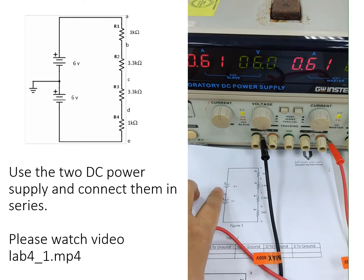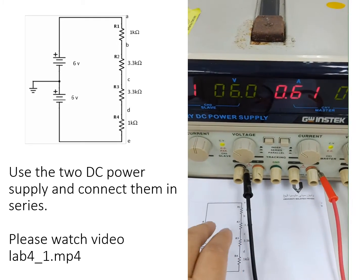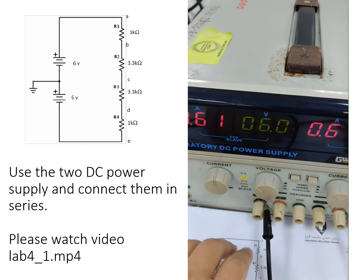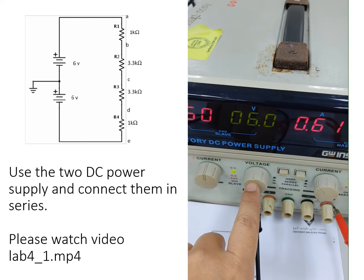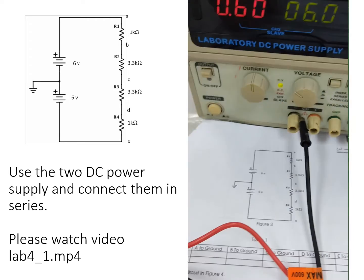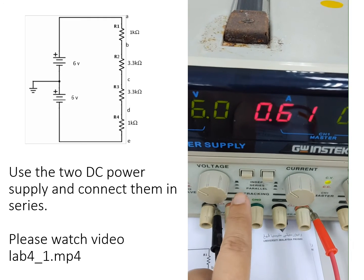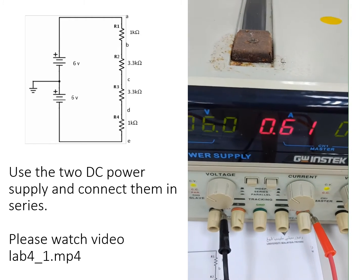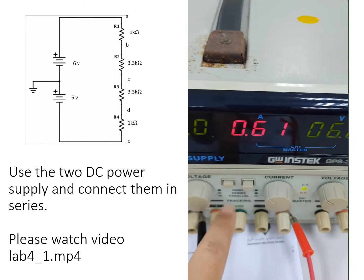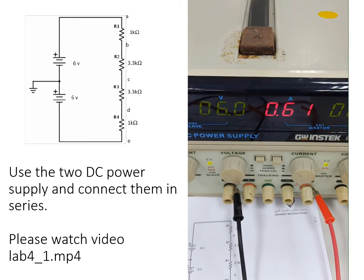When we want to use the DC power supply, we can see here we have the left and the right side. So this is the voltage. We need to set this one to 6 volt, and this one also 6 volt. Because our circuit is connected in series, we choose here, we have independent, series and parallel. So we choose series. We need to turn on this button to get the series connection. So it is already connected in series.